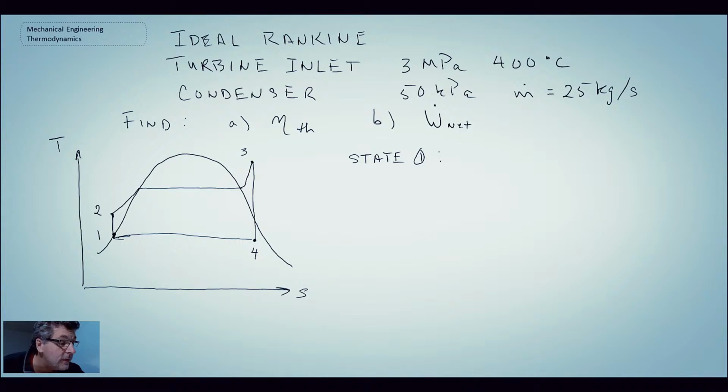You would be looking at saturated liquid or saturated water. We know this here is at 50 kPa, and this here is at 3 megapascals. So you go into the saturated steam table, saturated liquid, 50 kPa, and you pull off the enthalpy.